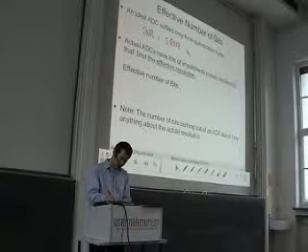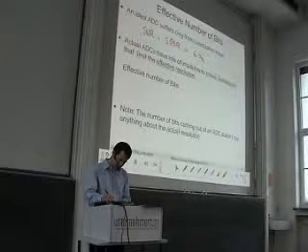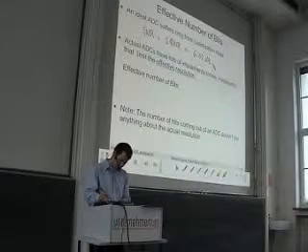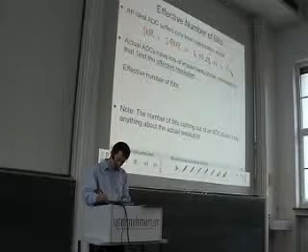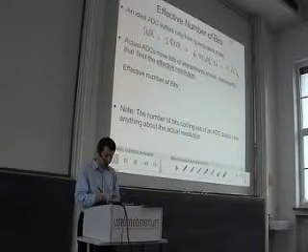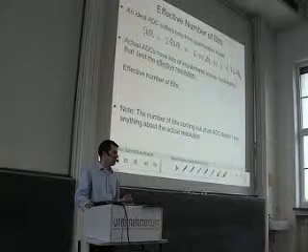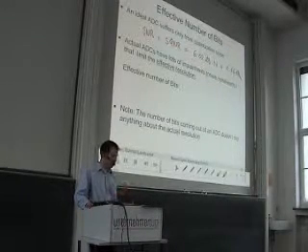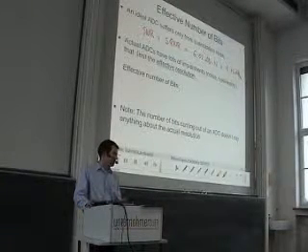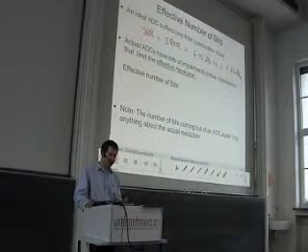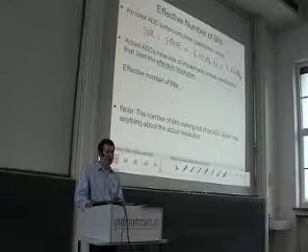This was defined, or we derived this as 6.02 dB times the number of bits of this quantizer plus 1.76 dB. So what this equation says, an ideal ADC without any noise except quantization noise, an ADC that has n bits, can provide a signal-to-noise ratio of 6.02 times number of bits plus 1.76.